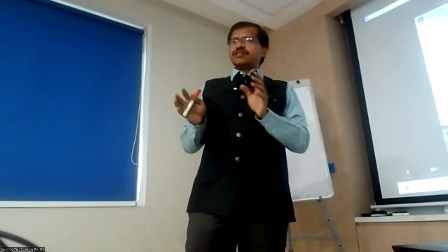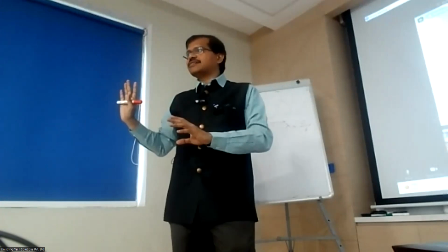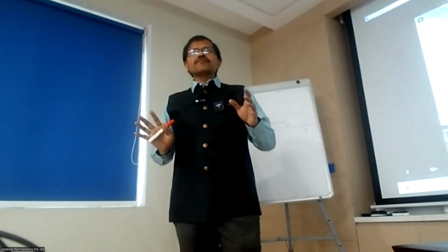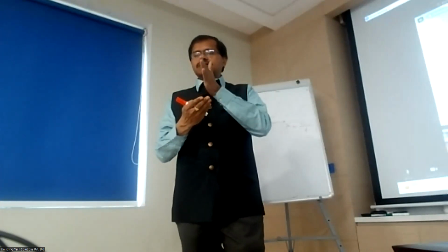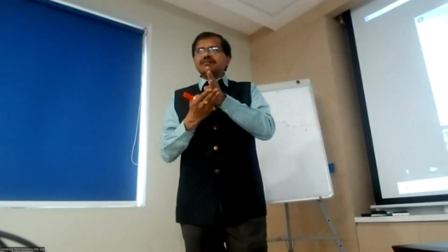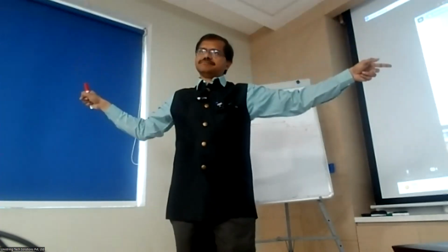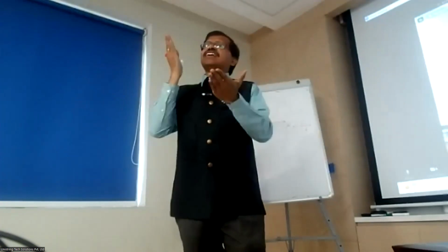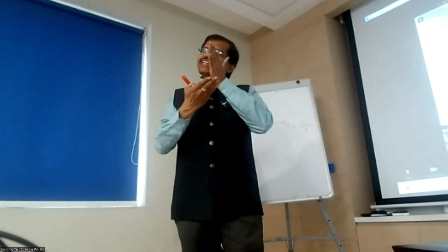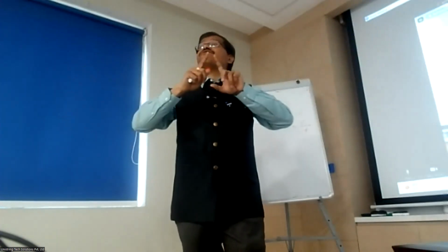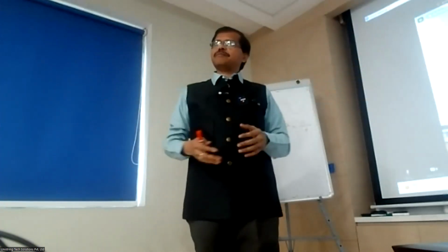Okay, let me put it this way so that you'll understand easily. We are not interested in deep theoretical physics. It's okay if you can read it, that's really nice. But from an application perspective, if you want infinite precision, or I will say very fine precision in frequency, you need an infinite observation in time. So when you want very detailed information in frequency, you need infinite time observation. And when you want very detailed information in time, you need an infinite frequency processing capable system. So I'll put a couple of examples so that you understand this easily.